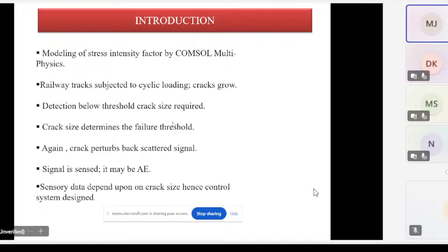Anyway, you can also use other techniques like the eddy current crack detection technique, but that's relatively static. Even laser or ordinary light you can use. Whenever some discontinuity is there, there's a fundamental law of optics: there ought to be some diffuse scattering. So that means the return wave will always be of lower intensity. So you can really get this.